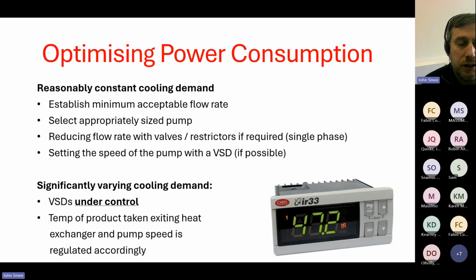Oh yeah, sure, it's grand, because it'll get the cooling job done and everyone is happy, because you don't have any technical issues. But as we can see from the affinity laws, if you're pumping more water than you need to, you're going to use way more electricity than you need to. So you will select an appropriately sized pump, or close enough to it. Maybe it's a little bit oversized, and then you can reduce your flow rate with valves and restrictors if required.